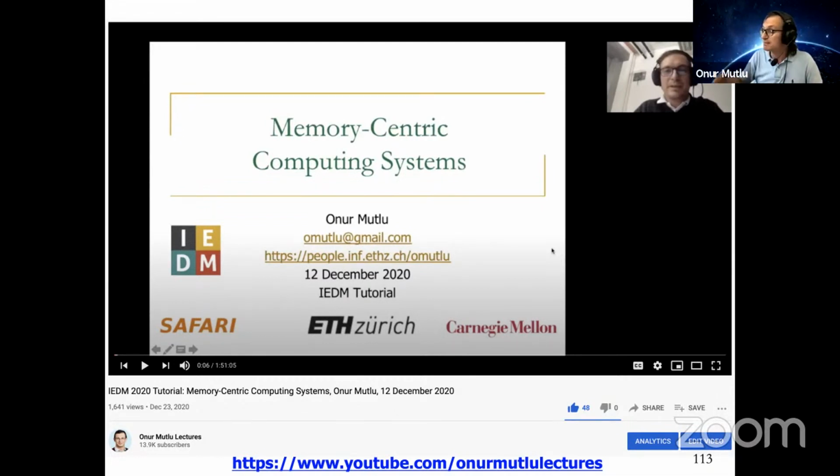Now, whether you can exploit that disturbance effect as a security attack that can take over the system, that's a much more difficult thing. You can, for example, try to exploit that in flash memory drives. In fact, we did that, but it's not easy because flash memory drives have a lot of levels of protection and error correction. Even though read disturbance effects are real and happen, a lot of the errors get corrected and they don't get exposed to the user. The fact that RowHammer happens in DRAM and you can exploit it is true because DRAM gets directly exposed to the programmer.